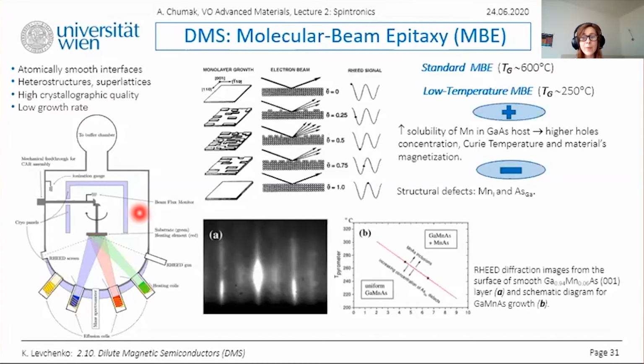During molecular beam epitaxy, non-interacting molecular beams of the constituent materials that we want to have in the end are evaporated from the effusion cells, and then they are allowed to chemically interact on a heated substrate, which is positioned here. The beams do not interact in the gas phase because they possess a mean free path much longer than the typical, usually 20 to 30 centimeters, source-to-substrate distance, due to the ultra-high vacuum conditions.